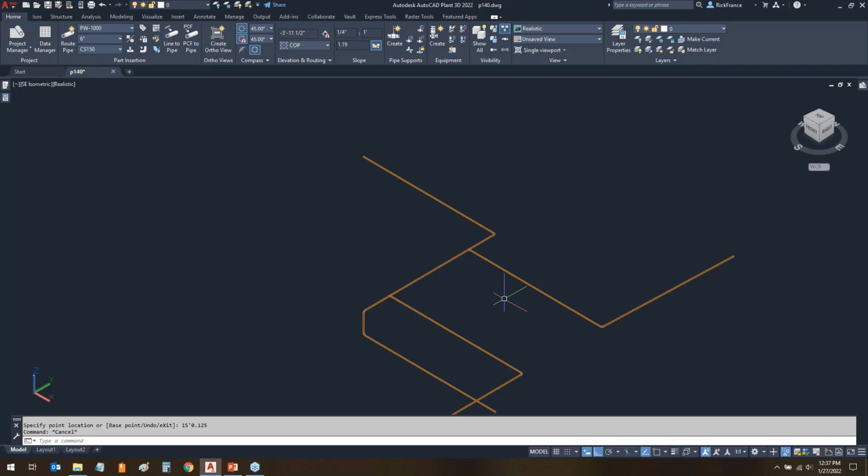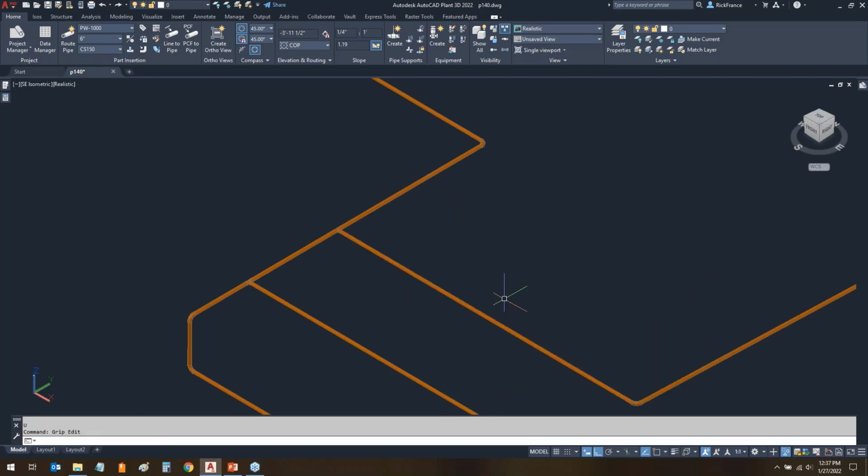So I could be as much as a 16th of an inch off. So I don't personally like that method because I'm trusting the rounding to be exact. And I don't know that it is. And I don't want to have to go check that and do distances with the units higher or anything like that. So that's the fastest method, but the least accurate.